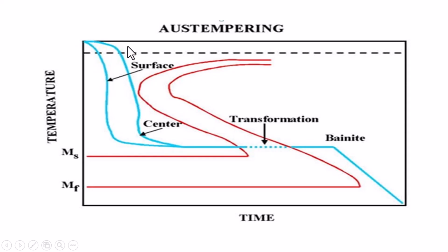Simply assume this is a stable region, with a dotted line above that. It is a stable range of austenite. You assume it is from the iron carbon diagram. What is austenite? That is the austenite we are taking in this range. Austenite is gamma iron in a particular temperature range. So we are suddenly cooling to a particular range of temperature, up to this range.